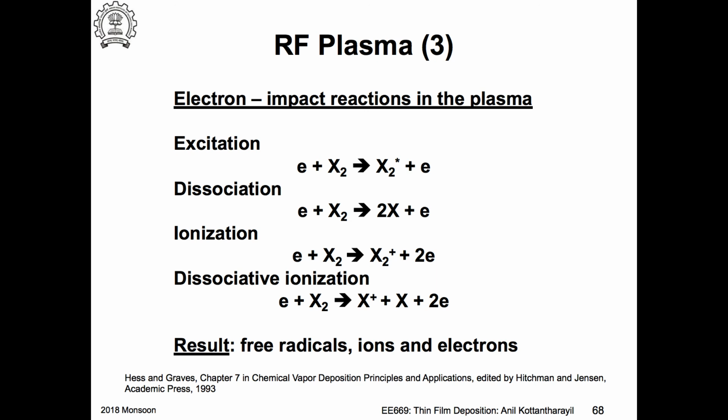But suppose it results in a volatile compound at the process temperature, then that goes out, because the whole system is under low pressure, lower than atmospheric pressure, so you are pumping it out. So depending on whether the chemical reaction leads to a solid material at that temperature or a volatile compound, you can get a deposition or an etching.